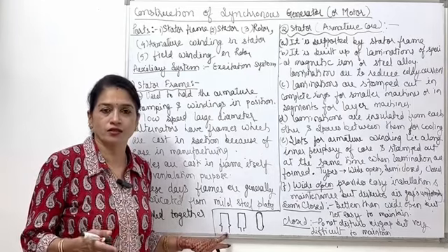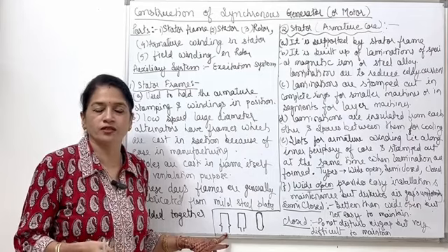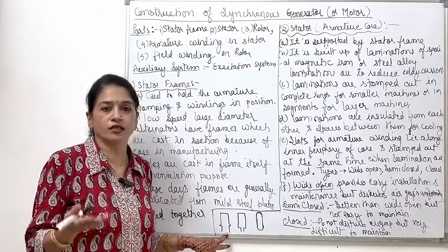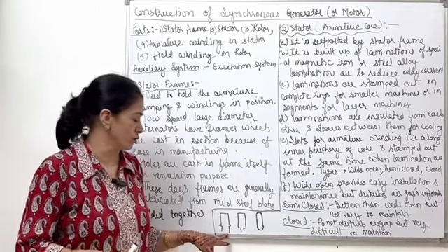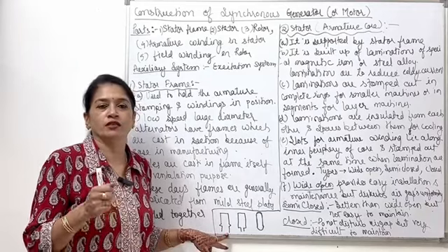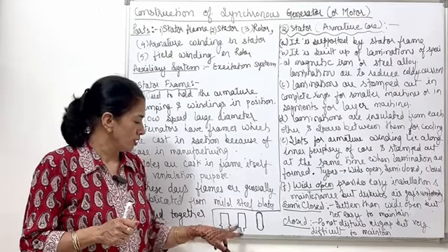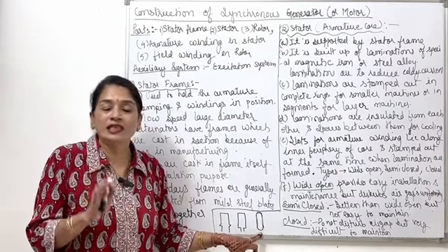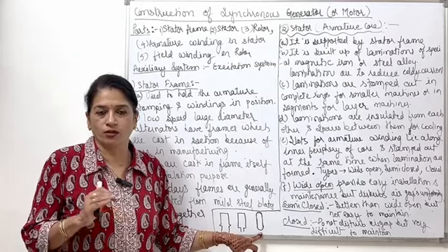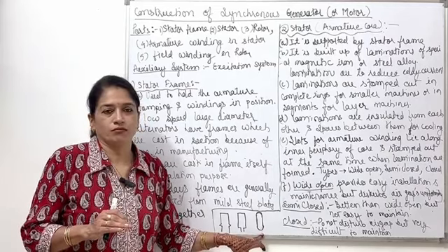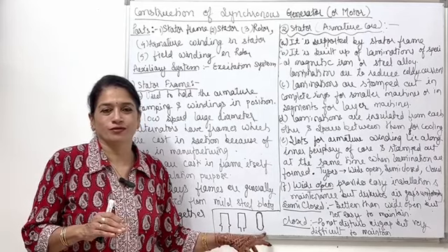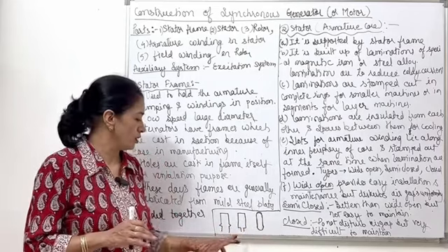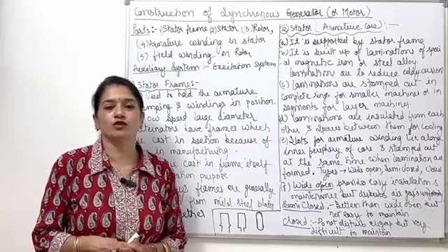It causes the production of ripples and harmonics in the EMF induced by the armature winding, and in the current provided to the load. So those EMFs and currents contain harmonics. In semi-closed slots, the harmonics are somewhat suppressed, while in closed slots there are the least chances of harmonics or ripples. But such closed slots are very rarely used; almost always the semi-closed type of slot is used.